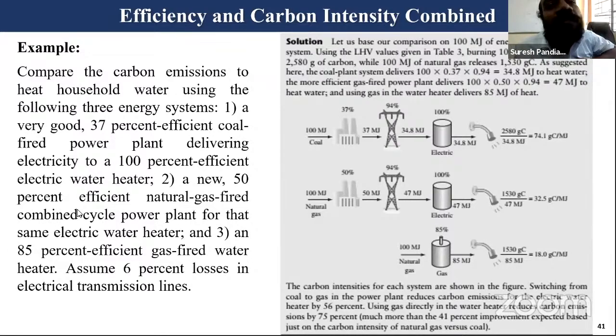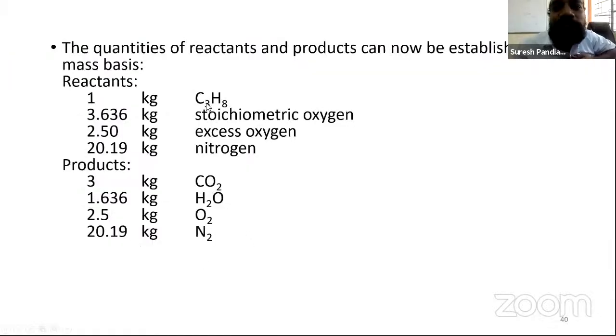Its capturing needs so much energy. Again, there are technological advancements, and scientists talk about installing a carbon capture plant with your power plant. If you add a carbon capture system to your power plant, then the carbon emission is decreased from 1 ton per megawatt of electricity produced. But the electricity required for carbon capturing, transport and storage means the entire 500 megawatt produced has to be spent on this unit. To give 500 megawatt output to the public, you need to produce 1000 megawatt. Where is the reduction?